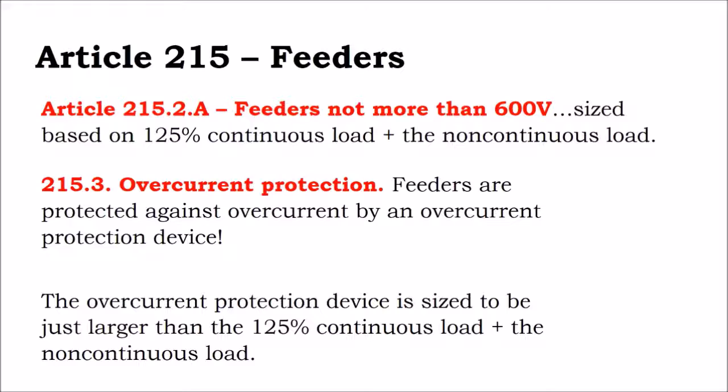But a fuse is also an overcurrent protection device. And so a fuse, as opposed to a breaker, will burn up and not work rather than just trip. You might say, well, why would I want a one-time use fuse rather than a breaker? And the answer is, well, cost. It's not going to happen often, and if it does happen, you want to know why it happened anyway before you really operate it again. A fuse may be perfect for the job, although breakers may be more simple. It also might cost more.